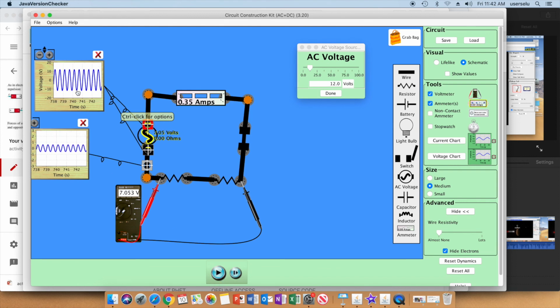Let me let it run a little bit more and let me stop them. But notice that when I'm at about 7.05 volts on the voltage scale, it's really hard to see. If I divide that by 7, I would get 0.35 on the ammeter scale. And so everything still works. And again, notice I'm going to be dropping half the voltage across that resistor and half the voltage across this particular resistor. Okay, so now let's look at some parallel cases.